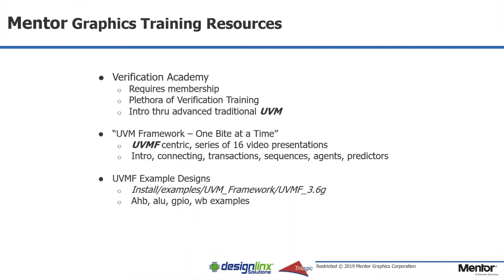So where do we get training for UVM or UVMF? The one-stop shop is Verification Academy. It requires a personal membership, but it has a plethora of verification training on not only traditional UVM, but on UVM Framework. And there's a 16 video presentation called One Bit at a Time. It's UVMF centric, and it really goes through the whole thing: intro, connecting transactions, all the way to how to connect a predictor and use it to the scoreboard.